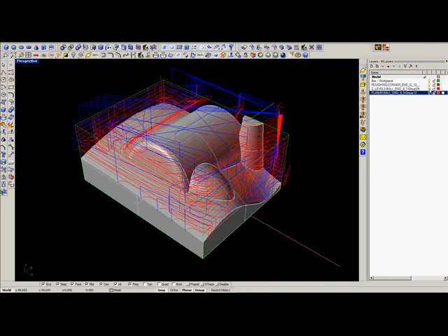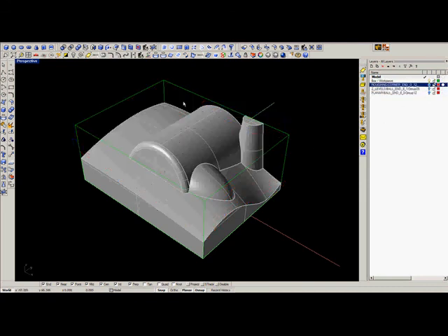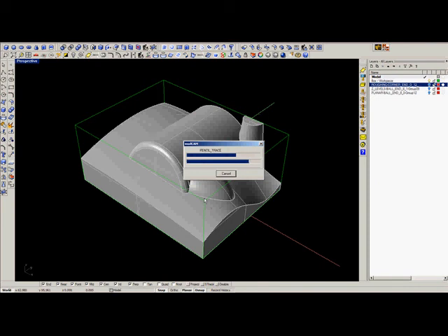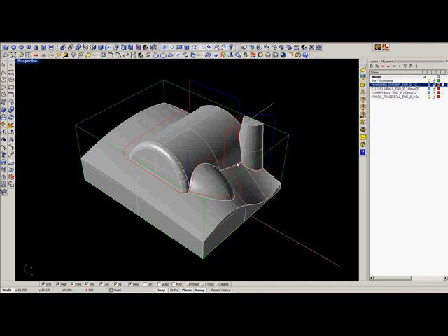We could also make a pencil trace to clean up, a dual contact toolpath called pencil trace. We can also use multiple Z cuts, but for this it's okay with only one path. And this is a dual contact toolpath that will clean up the regions in between the Z levels and planar finishing.